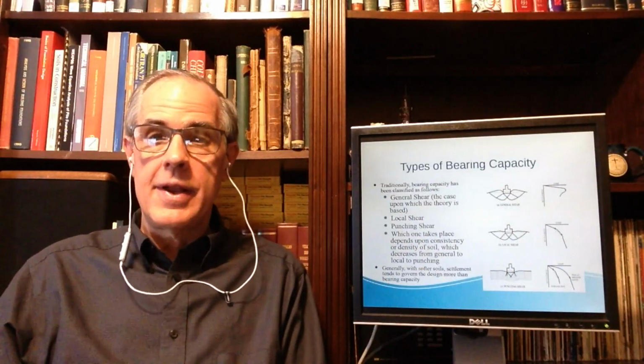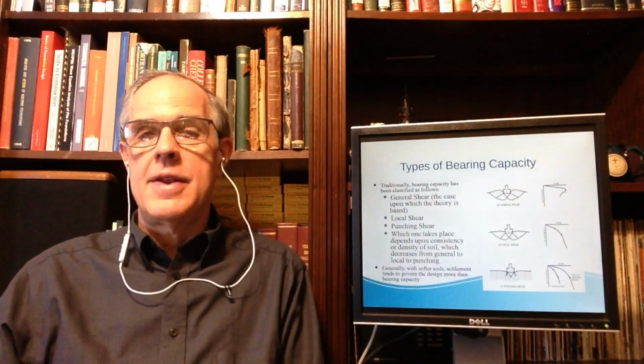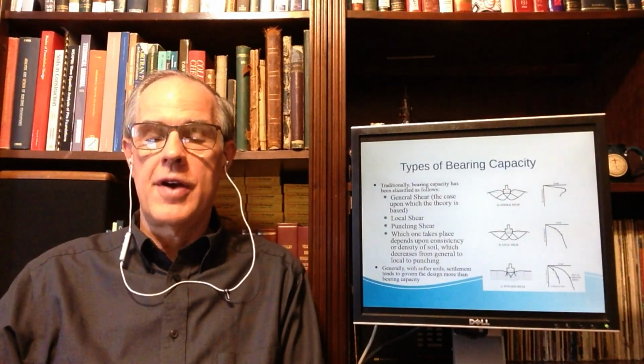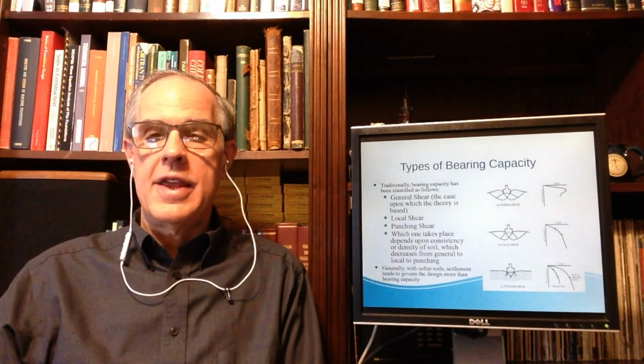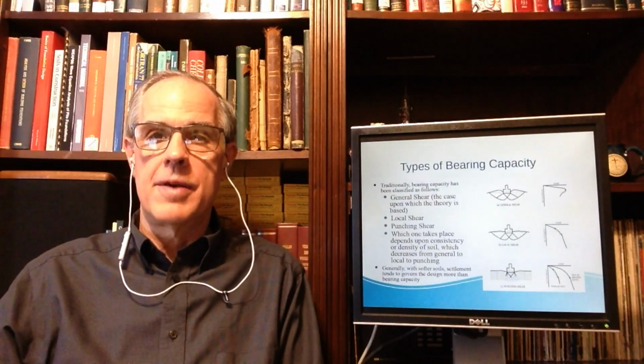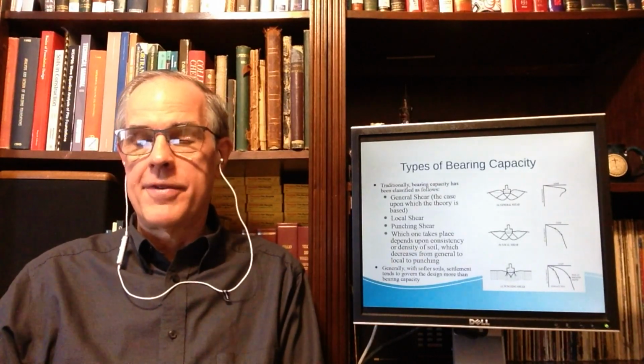And more importantly, the difference in settlement. There's some debate on whether we should really pursue this for softer soils. I think you will find that once you get into softer soils, settlement will become the governing failure mode. But we have to be mindful of this.